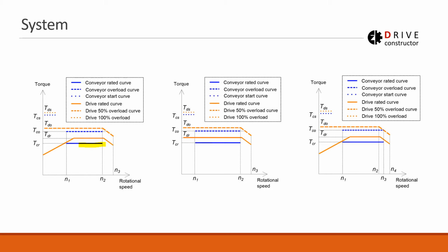So you see this torque is the first degree of overload, which can last some 30 seconds, for example, due to some conditions. And the other one is like the ultimate overload that can happen. It is very short term, but it can be double torque. So that means our system should be capable of handling all these overloads.